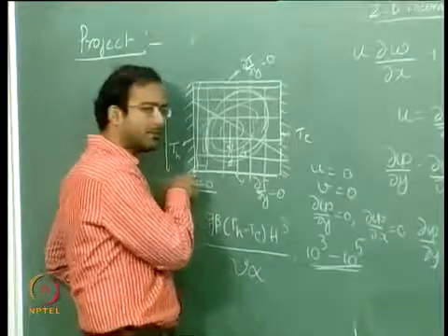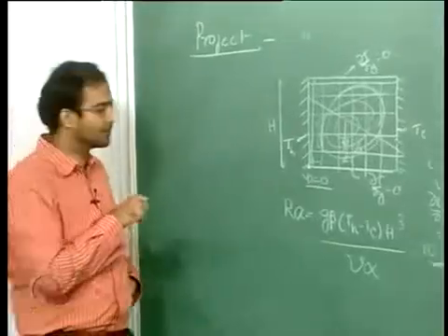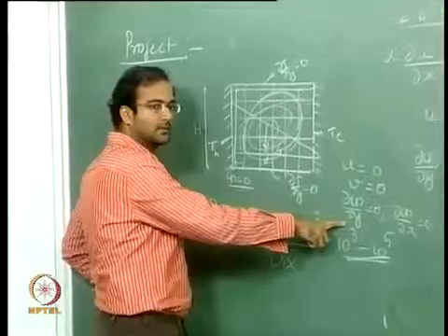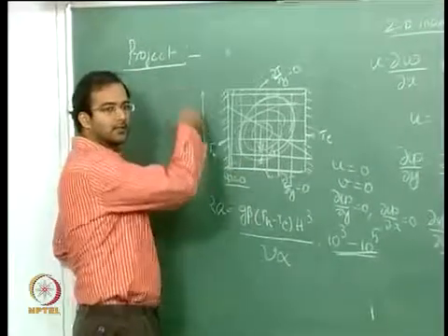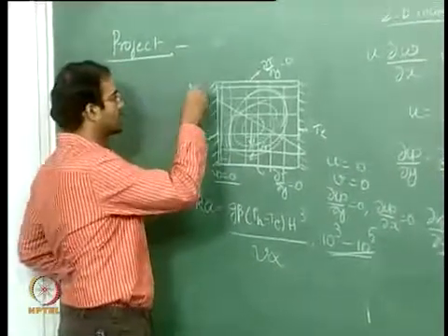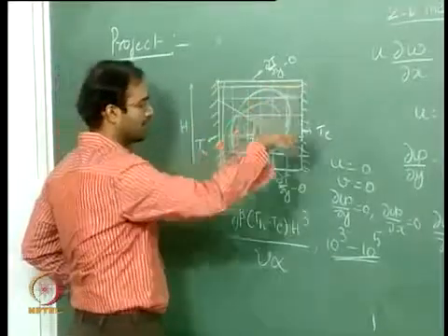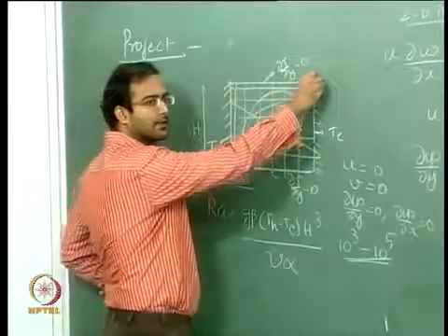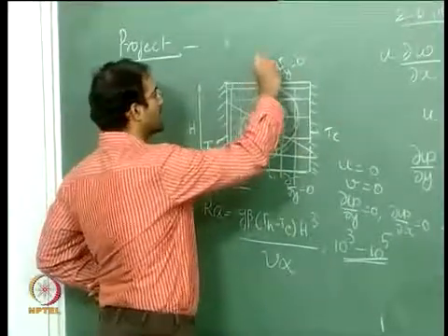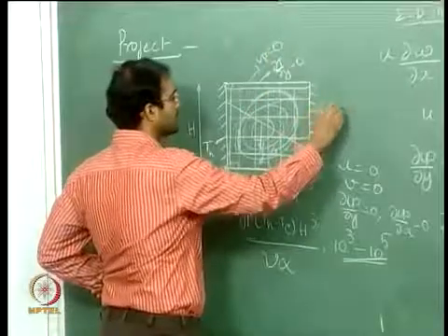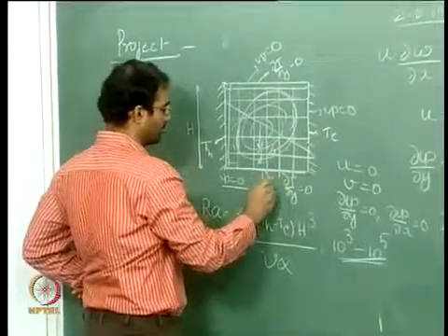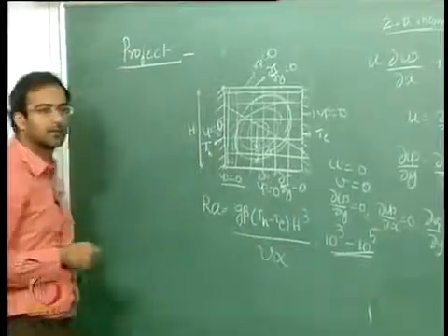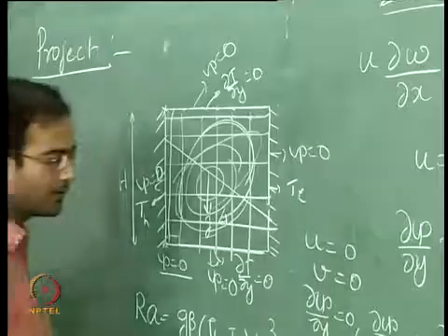So if you take for example the value here as 0, then you can look at this isothermal wall, you can apply d psi by dy 0, so therefore the stream function has to be 0 everywhere. So if it is 0 here, again for this wall you can apply d psi by dx 0, so therefore it has to be 0 here, even here. So in all the walls you can directly put stream function as 0. And for vorticity you can use the remaining condition.